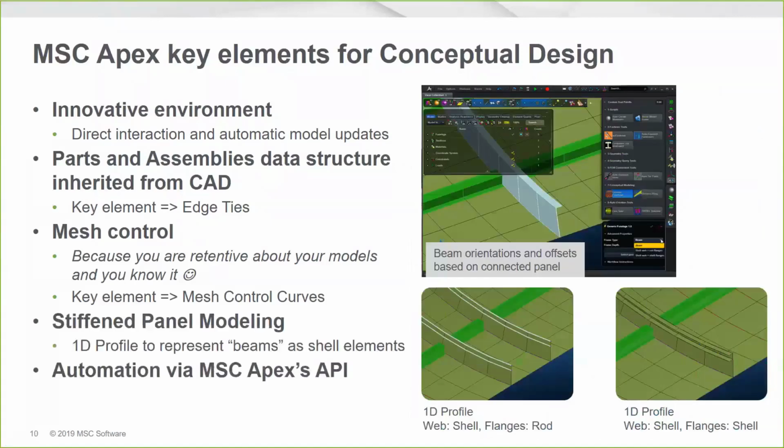Okay. Lastly, most of these structures are really stiffened panels. The kind of stiffener that's used depends upon who's making the model and what kind of behavior they're expecting from this model and what kind of stiffness they're expecting from this model. And so some people will choose to model the stiffeners maybe with just a beam element. Maybe it's just going to be a stringer that's a beam element. Some people will choose to just enter in area and inertia data. A lot of times that may not actually be formally known. We're just kind of guessing or kind of basing it off of past models that we have made.